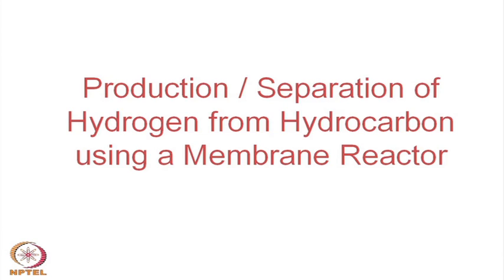So, if you have an oxygen ion conductor, as in the case of yttrium stabilized zirconia, then oxygen can pass through the material. So, it is a kind of membrane through which only a particular species like oxygen can pass through, no other gas or no other species.